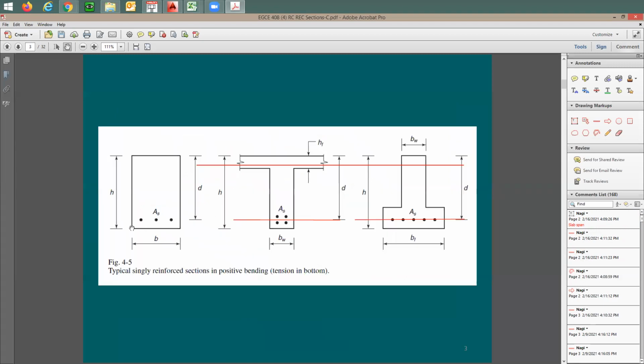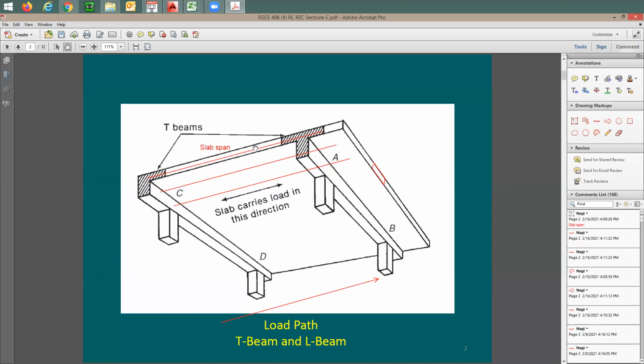So in a beam, you call out the reinforcing as the total number of rebars. In the slab, you call it by rebar size and the spacing. For example, I can come here and say slab reinforcing is going to be number 5, which means the rebar is going to be number 5, right? Number 5 at, let's say I'm going to throw some number there, 16" on center.